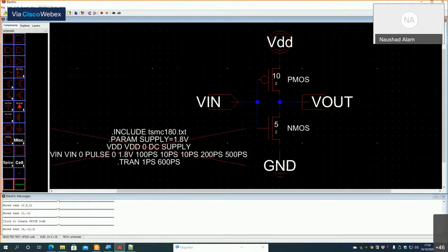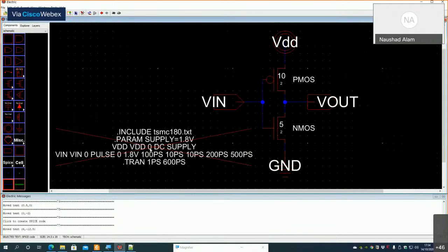You can again go to window and fill window. So you can see this command here. This SPICE code got added to this cell. Okay, now I hope we are ready for a SPICE simulation. We will edit this command for measuring various performance parameters. But let us first test, run it, and see that everything is working fine.